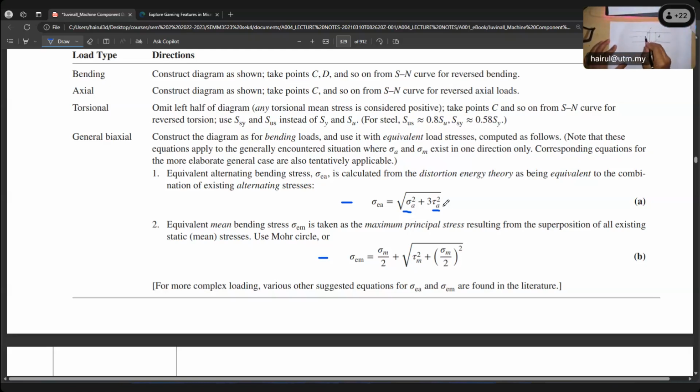When bending happens at the groove, you see this is the groove. Here it elongates more. The stress distribution goes kind of like a curve, then it goes straight. This one is compressed, but this one elongates, compared to a non-groove plane diameter. What is that factor? So when you have a groove, the stress concentration factor is much higher. Understand, class?